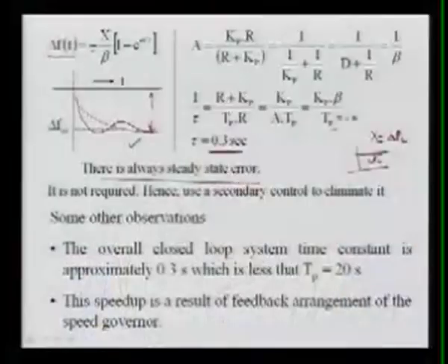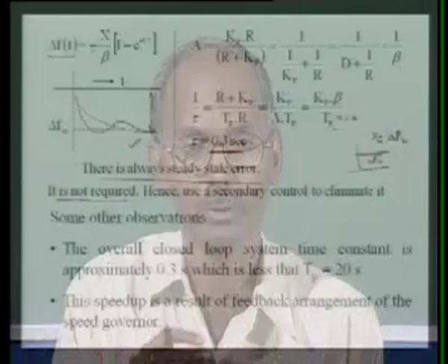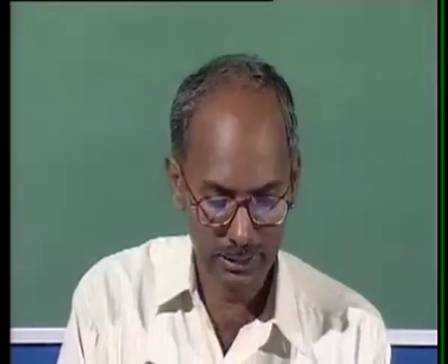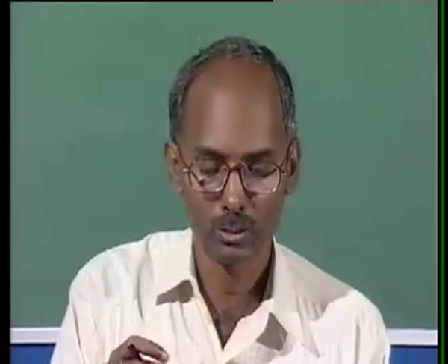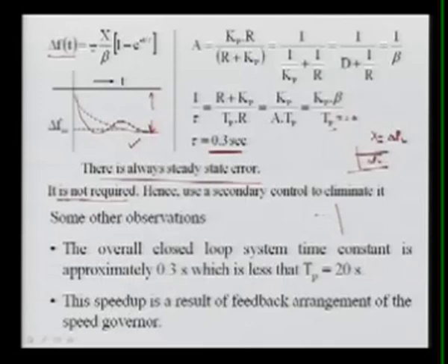So we can see that we don't want this steady state error. We want that once the load is changed, the frequency should deviate. Of course, only if the frequency deviates will the governor as well as the net load release act, and then we want it to come back. For example, I want this graph for the frequency change: let's suppose the load has increased, then the frequency should go back and settle to its normal value, that is, the change in F is 0.